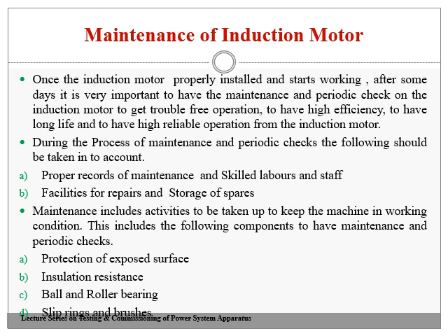Then, the proper insulation level or insulation resistance has to be maintained in both the stator and the rotor winding. If it becomes less than the specified value, we are supposed to go for drying off the induction motor. Then, since the shaft end is provided with a ball bearing as well as a roller bearing,